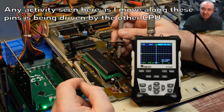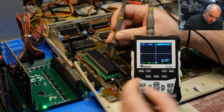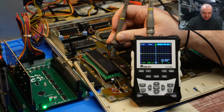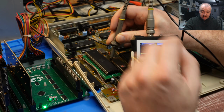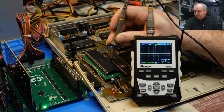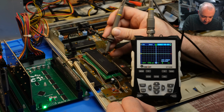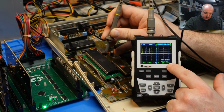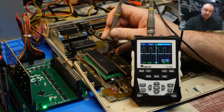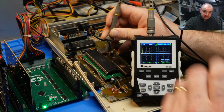Oh, I just managed to crash the system. But there it is there. Bus grant acknowledge, that is sitting low. Although this chip is still generating the E-clock for the system. That is on pin 20. And that's it there. It is quite a slow clock, only 700 kilohertz, but that's correct. I think it's 1/10 of the overall system clock.